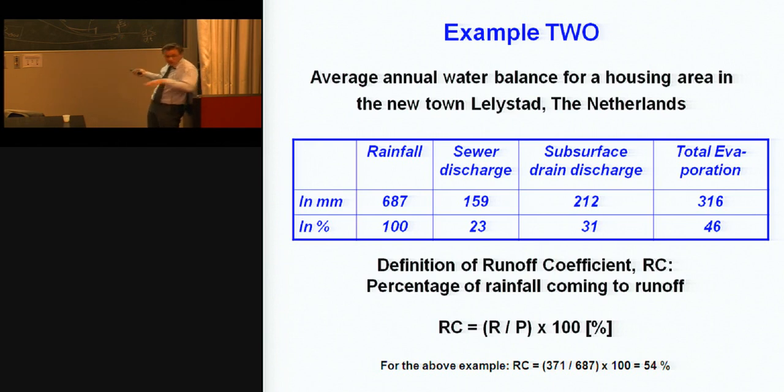This discharge is lost again. The groundwater recharge in Namibia, for instance, not all, but a significant part of that arid country, comes from a high runoff coefficient locally, but then the discharge flows in the river and goes back to the groundwater. It's infiltration of river water into the groundwater, which is very common in arid areas. So for the whole of Namibia, you have a much lower runoff coefficient.